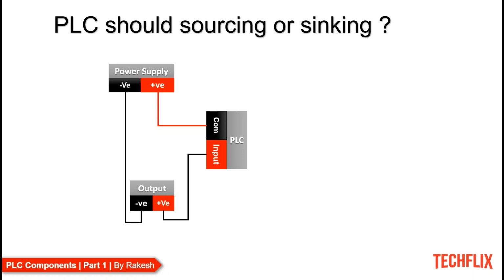Now, imagine when the PLC needs to give a digital output, for example, opening or closing of a valve. In this case, the best practice is the PLC should be sourcing while the output should be sinking. The reason here is safety. As shown, the PLC is sourcing and the output is sinking. In this case, if the cable from output to PLC or source breaks, the circuit would be open, and the output will stop. Even if the output stops, it will not affect other loops of the PLC program, as compared to the input given by the sensor, which is used to process the PLC program.